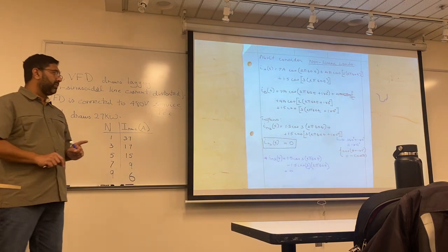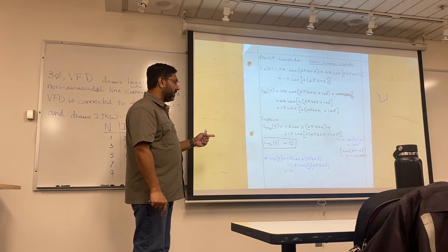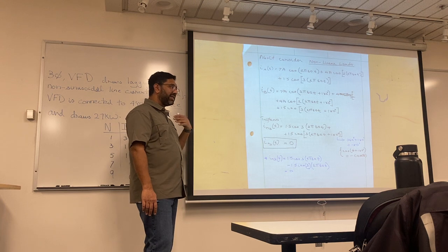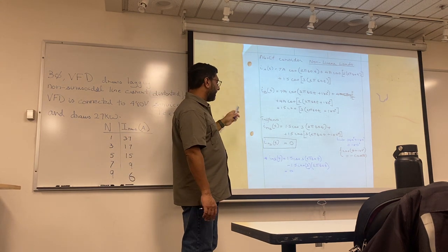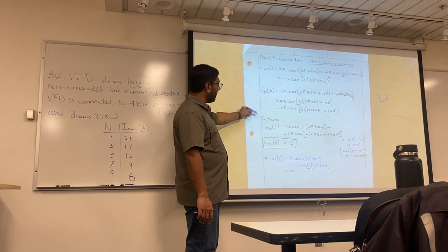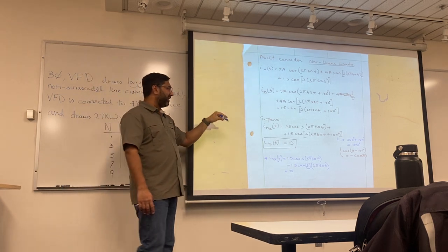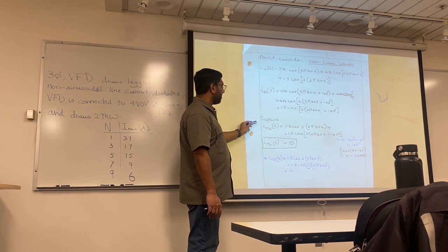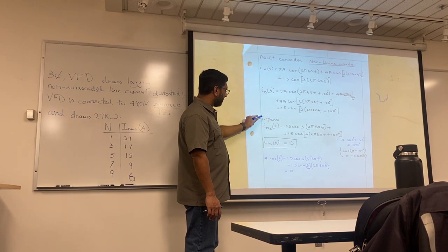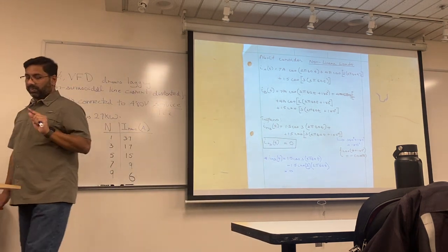Now we don't discuss this with our technicians because they don't need this, and I don't think anyone in their homes is actually running big SCRs or SMPS that our technicians need to know. But two-phase, keep in mind, it trips me whenever I see that. People just really start saying, hey, triplen, so make the neutral 3 times and all that. Keep in mind that's true for 3-phase, not true for 2-phase. For 2-phase, in fact, even though we call them triplens, your neutral is 0, which is very good.